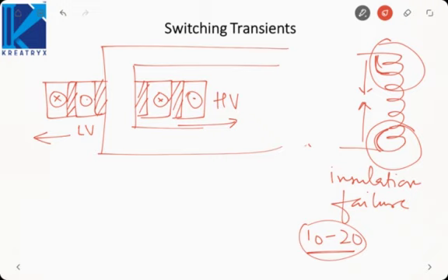So windings should be provided good support, otherwise they will be dislocated. So it can lead to dislocation of the winding. Why will windings be dislocated? Because a high amount of force is being generated on the winding due to magnetic inrush current. Why is it being generated? Because forces are not being balanced, since this current is restricted to only one side of the transformer and not both the sides.